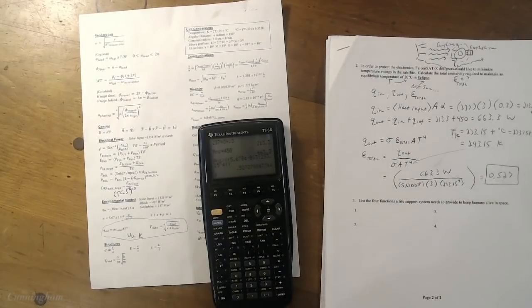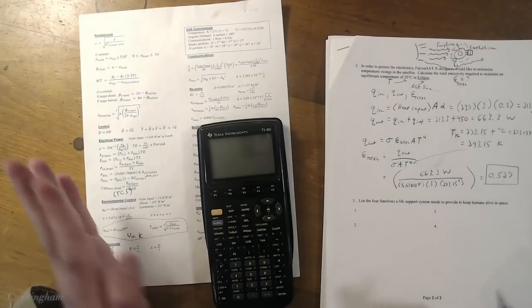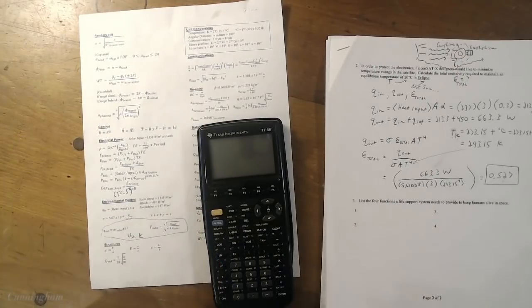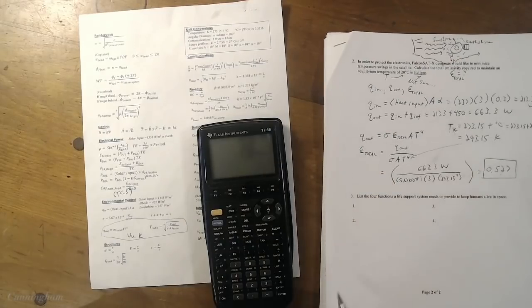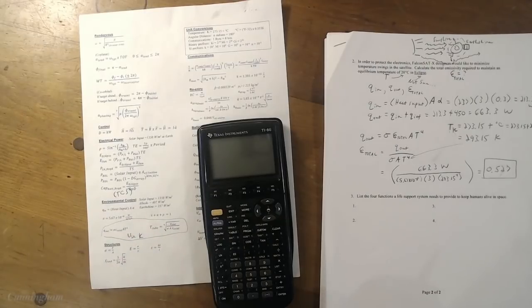Okay, just to recap, what we found in the first problem was the equilibrium temperature based on us being in the sun. In problem number 2, we could have been given the emissivity and looked for the equilibrium temperature. You know how to do that, but in this case we were given the reverse: here's the temperature we want to achieve. How emissive do we have to be to achieve that temperature? And then they said, not only that, I'm changing the situation on you. You've gone back behind the Earth, so now you're in eclipse. As you can see, the processes are actually really similar. That's why there's only a couple of equations right here for TCS, for thermal control.